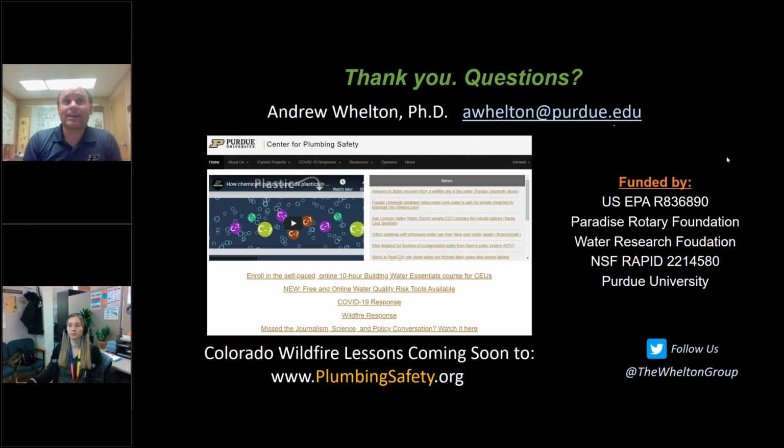So there really isn't that good of evidence out there either way. So generally what I assume is that if you have plastic pipes in the system, whether it be iron-coated plastics or hardness-coated plastics, you assume that there could be contamination until it proves you otherwise. But that's a great study that somebody could do. They could coat the pipes, put in contamination, let it sit, desorb it, put in clean water, and see if it leaches out from the plastic. That'd be a great study.